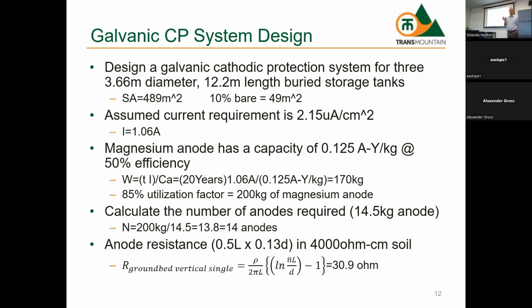If we were to space them 2 meters apart, 2 meters, 2 meters, 2 meters, we can now calculate the soil resistivity at a depth of 2 meters. So yes, you would test the soil to get a resistivity value. Otherwise, you're assuming and just throwing a number in the equation, and you're not going to get an accurate result. So at all costs, if possible, go collect the soil resistivity reading.